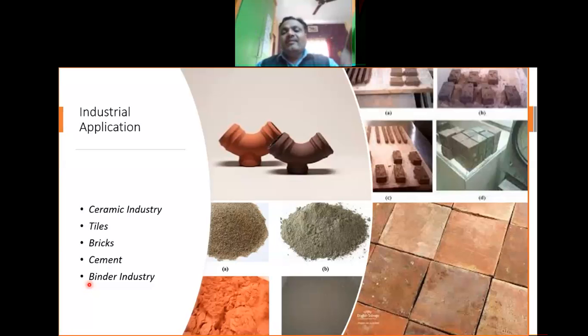There is a presence of a few heavy metals, so not for drinking water, but this may be the cheapest source of coagulant for treatment of wastewaters containing dye, as there is a combination of both aluminum and iron. We produced some quantity of coagulant and we found that, compared with individual aluminum or iron, this was a very good coagulant for removal of dye from textile industry wastewater.